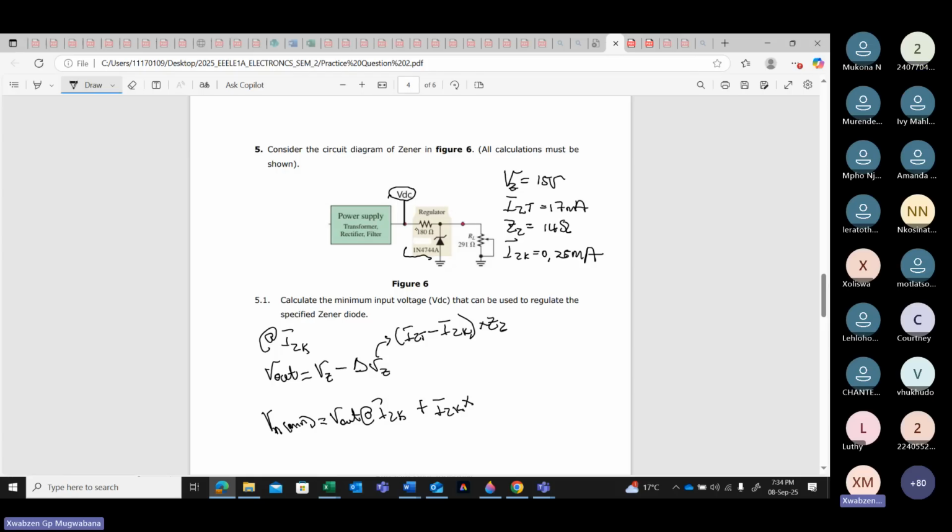Then there is this load resistor connected there. Remember, this voltage plus this voltage must be equal to the supply voltage. That is Ohm's law. I must add that regulator resistor, the R limiter that I see there, so I multiply this by 180 ohms. Then I will know what my minimum input voltage will be. Are you having a problem with this equation here?